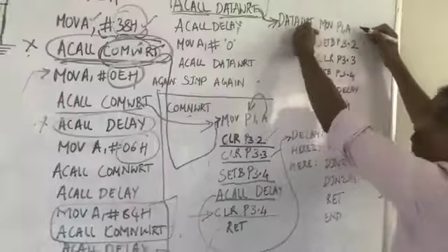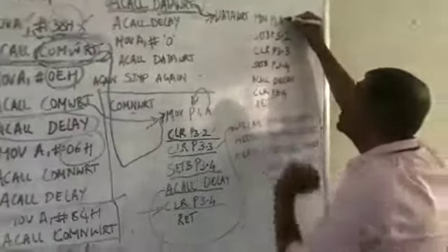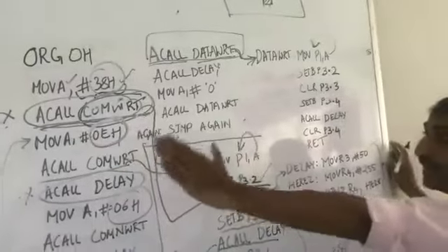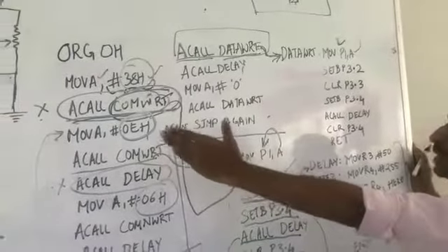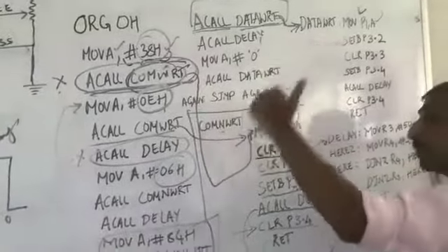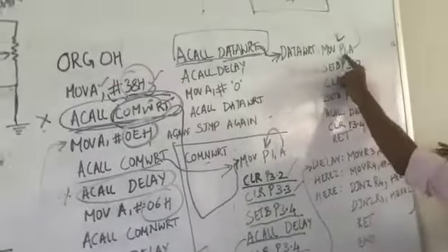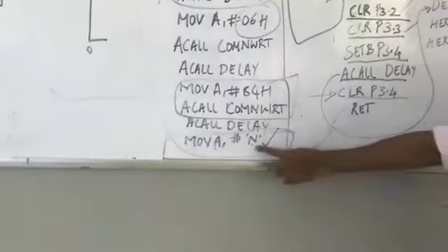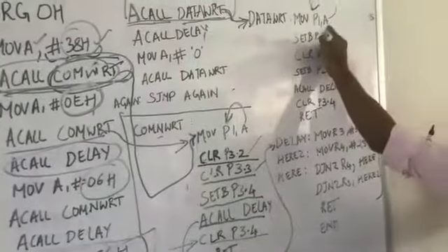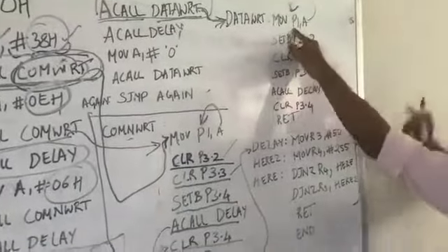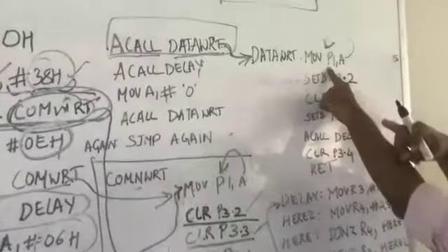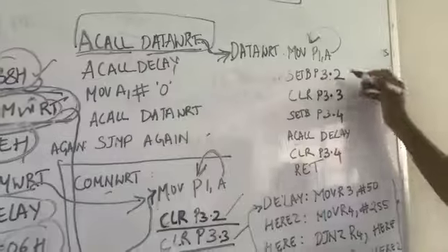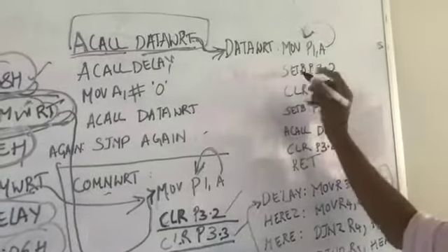Here what we need to do, this time whatever is there in the accumulator, we again take it into port 1, because the data that needs to be displayed is again sent from port 1 itself. Therefore, the accumulator content, which is N, I wanted to display N, I had taken it into the accumulator. From the accumulator, I will send it to port 1, so that from port 1 only it will come to DB0 to DB7. Okay, but this time what do I need to do?